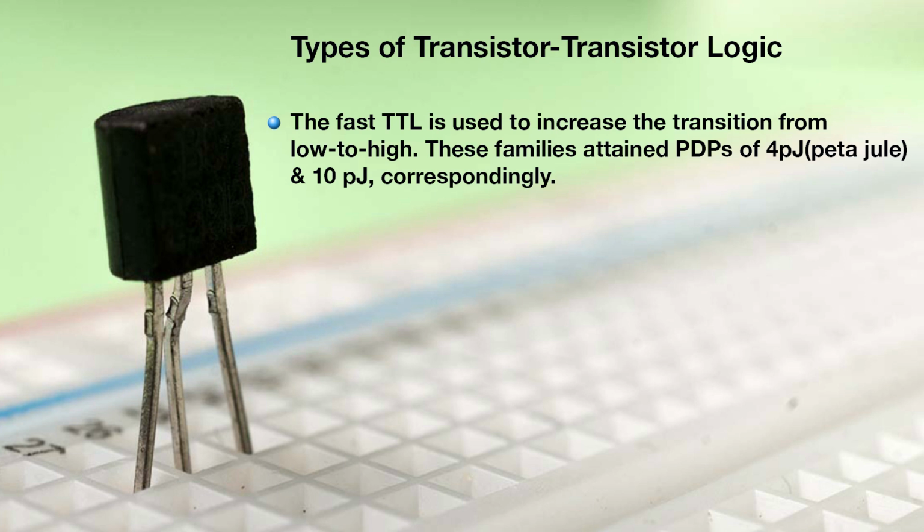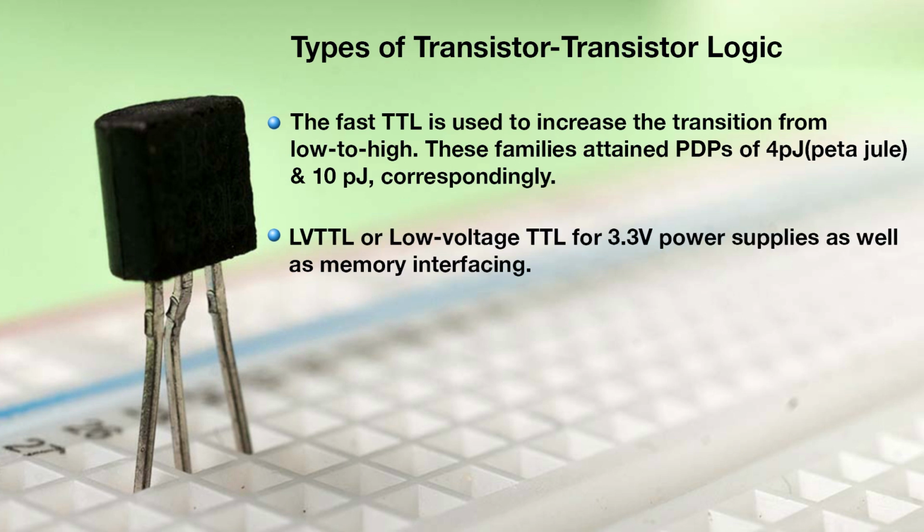These families attain PDPs of 4 picojoules or 10 picojoules correspondingly. LVTTL, or low voltage TTL, is for 3.3 volt power supplies as well as memory interfacing.